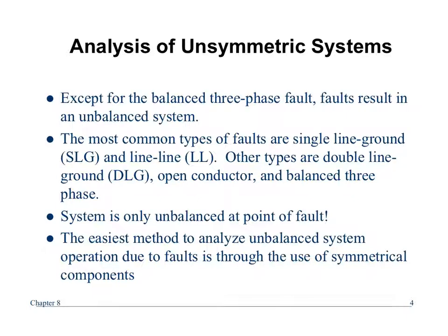I will say when you do protection system design, you almost always set it as low as practical. And that's kind of a misnomer because every time I've seen it, arbitrarily set it to 1 amp secondary pickup and have a short time delay to coordinate with other elements. So it's pretty arbitrary for ground fault. There hasn't been a lot of research or discussion done, but it's something that we can talk more about if you take Power 3. So anyway, we're going to assume that the system is perfectly balanced everywhere else except the point at the fault or where the fault occurs.